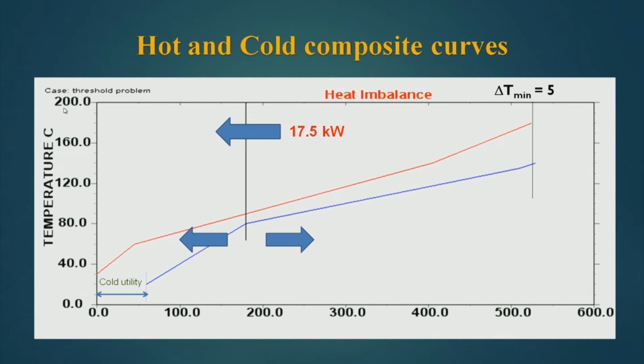Now, this shows the composite curve of the problem. Here this is the hot composite curve, this is the cold composite curve, this is the process pinch area and this is the pseudo pinch. So, why process pinch here? Because no heat flows here, hot utility requirement is 0.